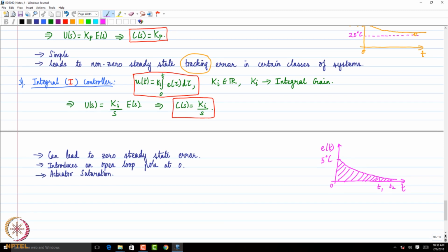For example, if I want a linear motion system in some machining assembly, and I purchase a motor based electromechanical actuator which can provide a maximum of 100 newtons, now I program a controller which at an instant of time asks for 1000 newtons. I can't realize it in practice. Then I reach actuator saturation. With such a controller, although in theory I might be satisfying some performance requirements, in practice I would not be able to reproduce them.